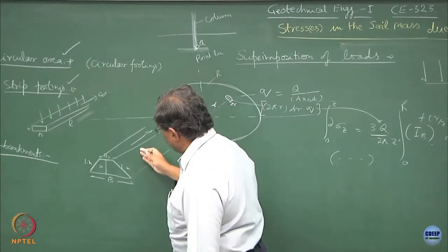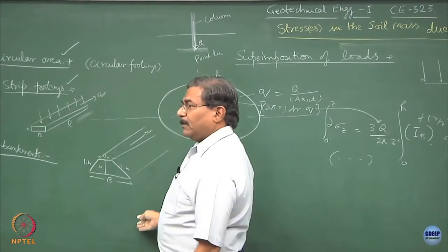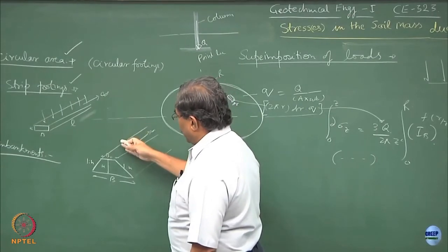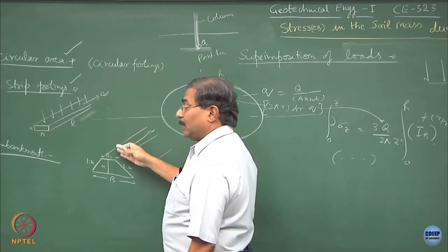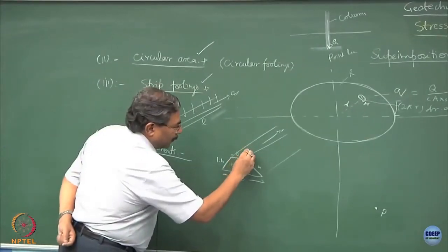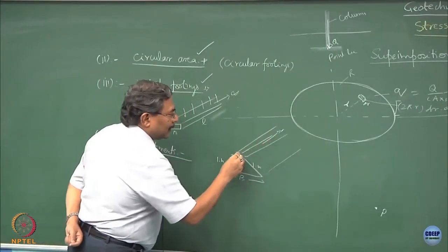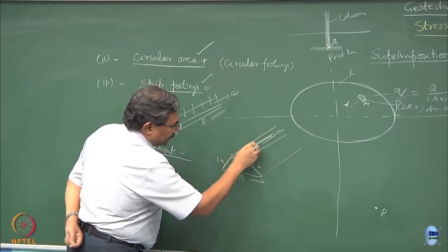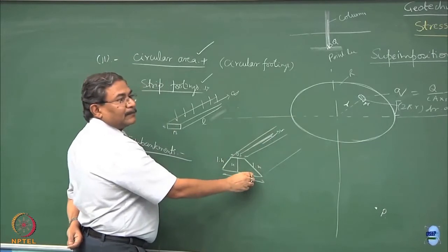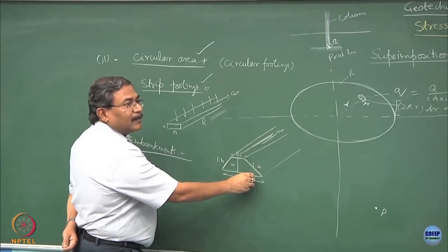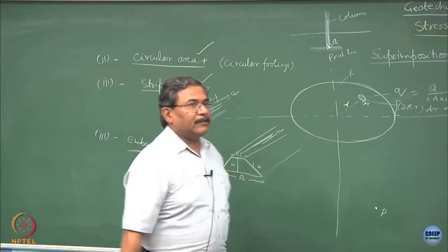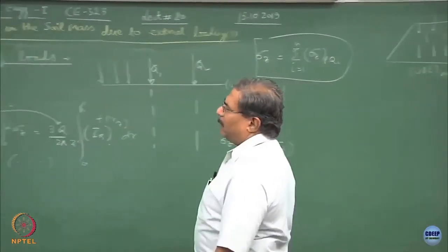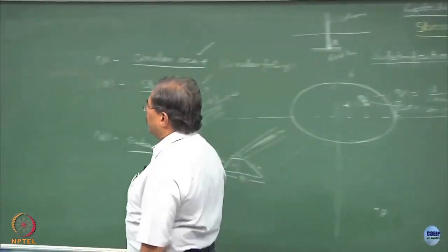So suppose if I ask you to find out what is the state of stress at the bottom point, no problem, you can still model it. The entire loading can be, now there is a trick. The load is going to act over here, the railways are going to run over here, the roadways are here, okay, aircraft loading is here. We have to delegate this stress at the base of the embankment, clear? I use the word delegation. A better word for this is dispersion of the loading.